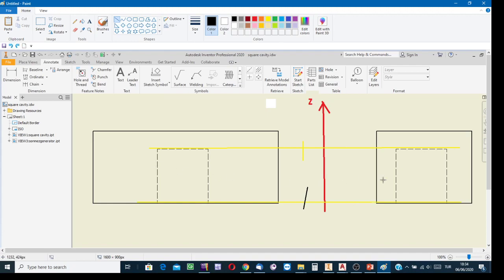But in our case, it is not an exterior feature. The hidden entity is an interior entity. So since it is at the inside, it cannot be a solid feature. It must be an empty space. Making such an interpretation can be done knowing the ABC of orthographic projection, saying this is the front view, this is the left side view, and concluding that within the rectangular prismatic object, there is a rectangular prismatic empty space.